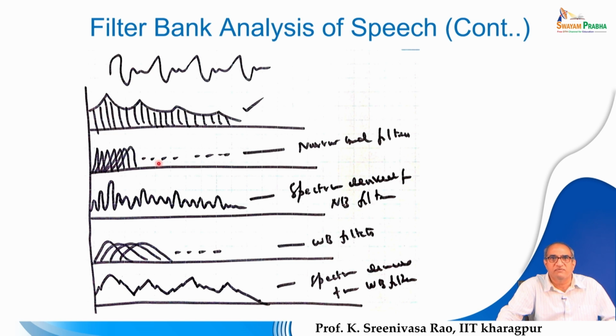So, by using these narrowband filters, how do you derive the spectral information? Here you can see this is the set of narrowband filters. At the output of each narrowband filter, we see what energy is associated with it. If you plot the energy values associated with each narrowband filter, you can get this particular spectral envelope. Since we are using narrowband filters, at the output you can also observe finer variations, known as the pitch harmonics, present as part of the spectral information content of the signal.